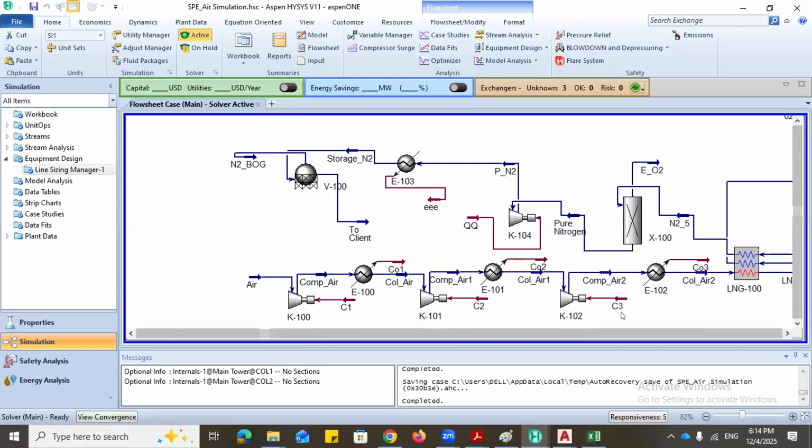So when we are doing our P&ID development, we have stages of P&ID development, I think about 30%, 20%, 30%, 10%. At each percentage, there are required activities that must be done in the full PFD, and it must be approved before we move to the next stage. So our P&ID has about four major stages. I think in the third stage, this is where we fix in all the necessary hazard analysis and all the process safety analysis that has been done in the facility or in the plant.